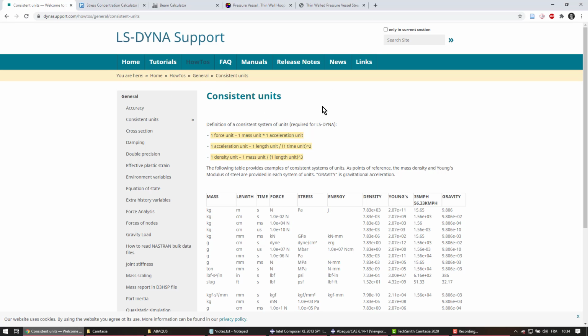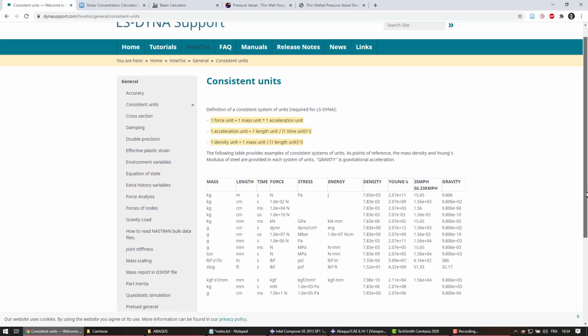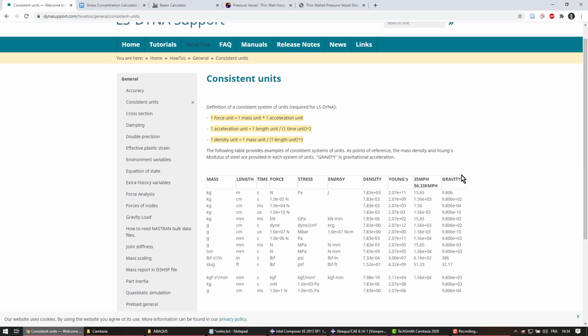That explains a bit what unit consistency is. Abaqus will expect you to input units and values that are coherent with each other. So here, if I decide that 150 is in meters, I'll need to use kilos, seconds, and Newton. If you maintain the right scale for each of them, you'll obtain the right answer. Like let's say if we divide newtons per meter squared, we would obtain pascals.